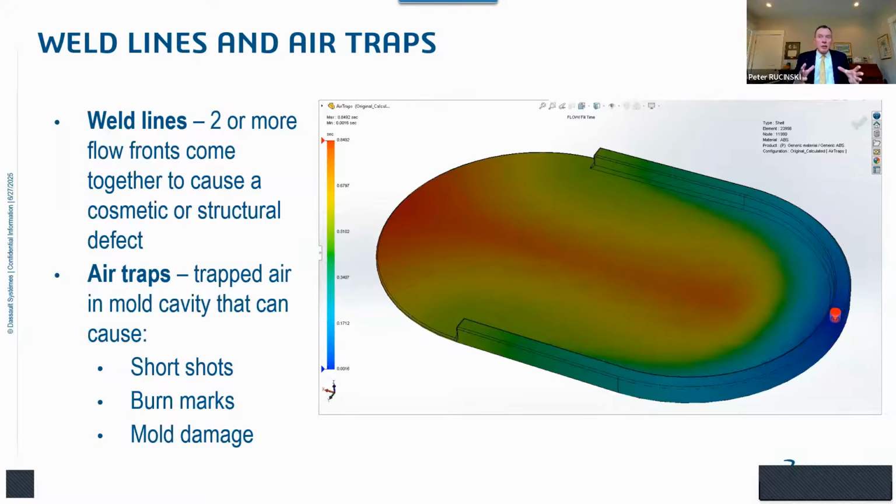But sometimes you can have air that gets surrounded by the melted plastic. It gets compressed as the mold continues to fill and pack. And if it gets compressed enough, there's a small explosion or combustion inside your mold cavity. If it gets to that point, and by the way, this is a completely unacceptable defect.